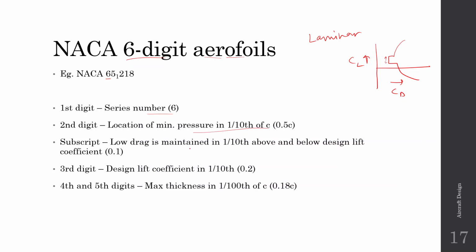Low drag is maintained within 1/10th above and below the design lift coefficient. Here the subscript is 1, which means that above and below 0.1 of the design lift coefficient, it maintains low drag. So this is 0.1 and this is 0.1, the gap.